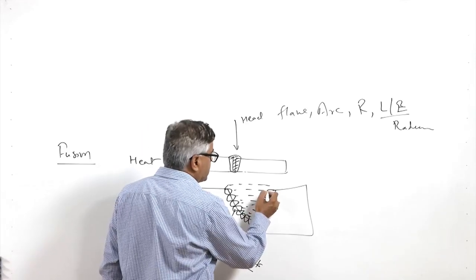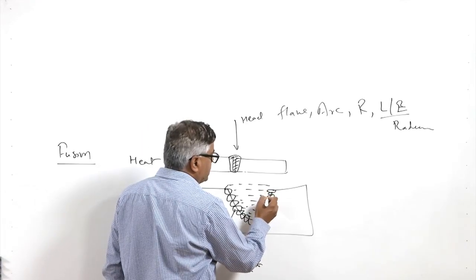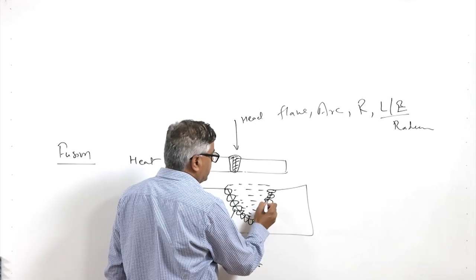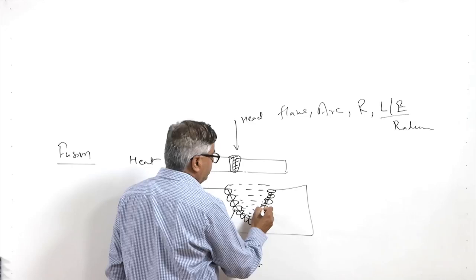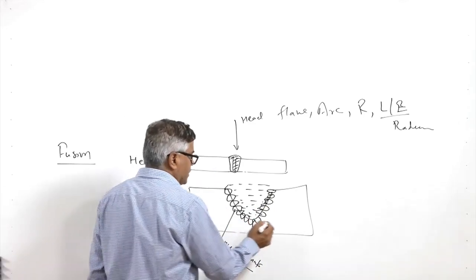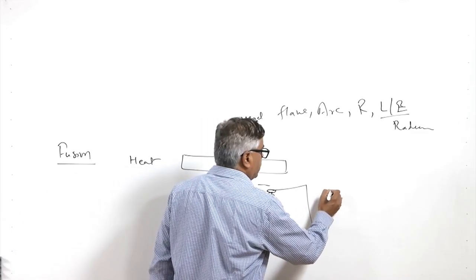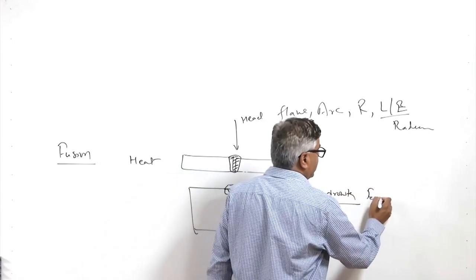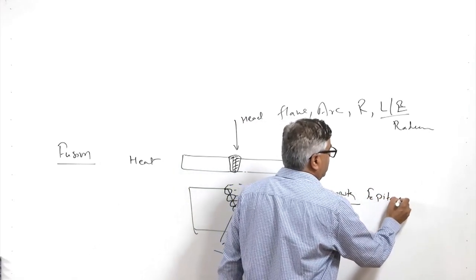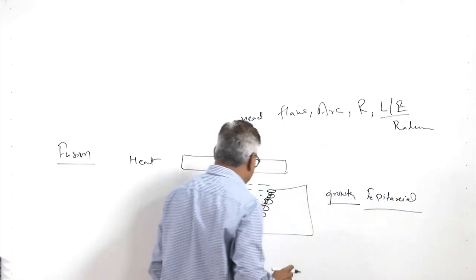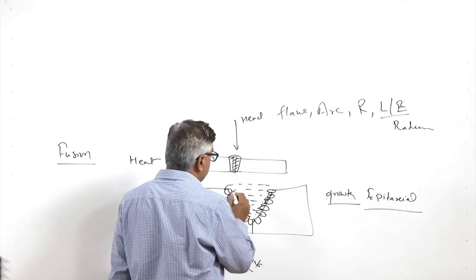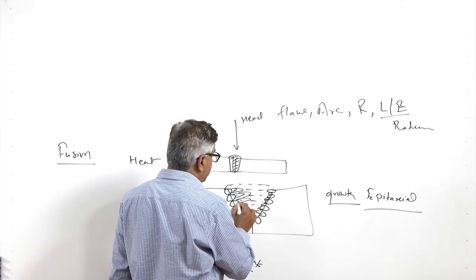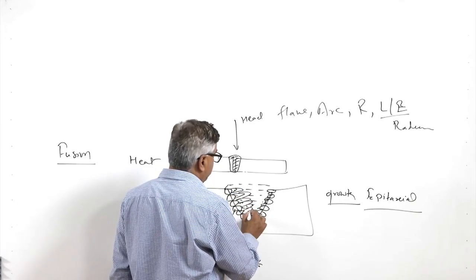So, in cases where the base metal is just brought to the molten state, solidification occurs directly by the growth approach. This is called epitaxial solidification, and gradually the entire amount of molten metal is consumed by the growth of these grains during solidification.